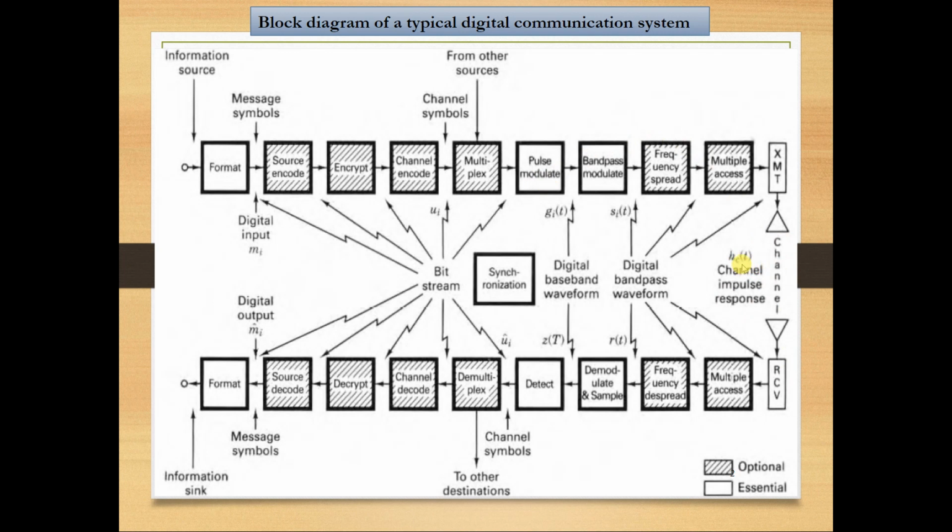But if you choose it randomly, without any justification, then most probably your pulse will not be the ideal, the most suitable pulse to be used, and therefore you may degrade your transmission, reduce reliability, cause errors, and make it difficult for the receiver to decode it successfully.